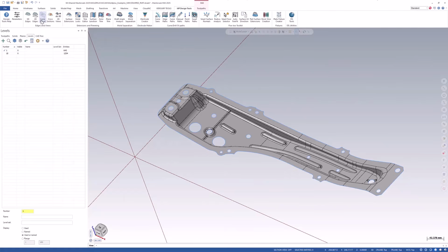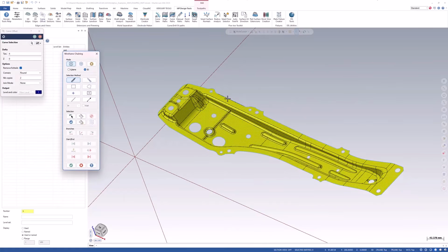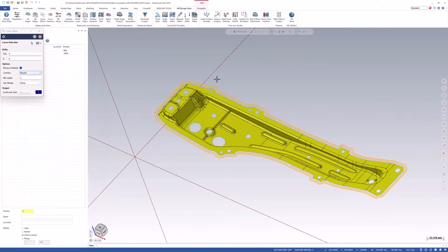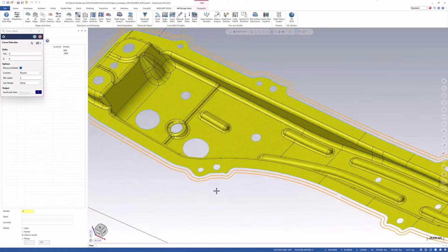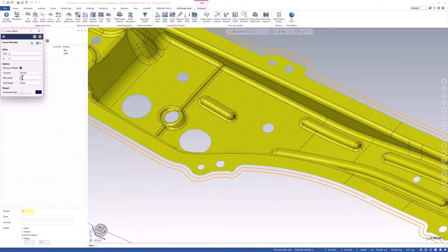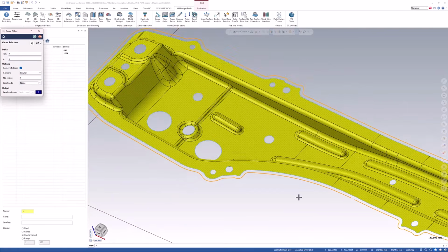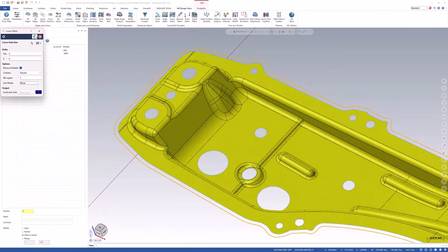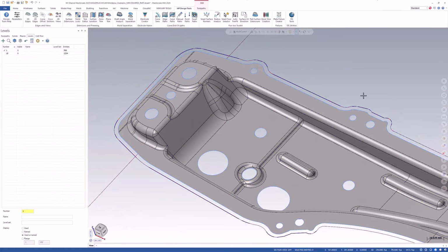Let's say you're going to trim it in a couple spots. So we can go ahead and chain all around it. And then there you go. A couple copies at 4 millimeters apart. This one I think is a metric one. So yeah, a couple 4 millimeters apart. Z's on 0. And then a couple copies spread out. So we can always go to 1 if we need to. And it pretty much offsets the whole thing. Pretty quickly and easily, we're done, we're prepped, we're ready to start programming.